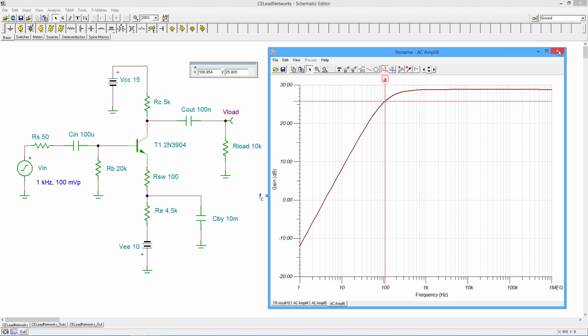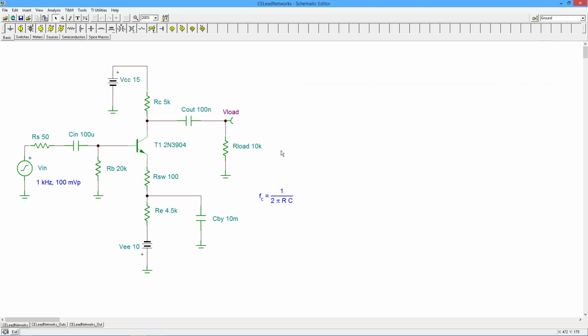Okay, what's next? Well, how about the input network? It's going to be the same sort of deal. This capacitor is going to drive a load impedance looking this way, and then whatever's behind it. So we're going to have a source, RS, which is only 50 ohms. It's not going to have much impact. And then whatever the Z in over here happens to be, all right?